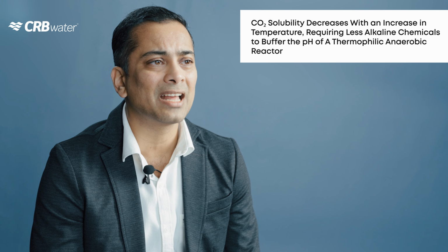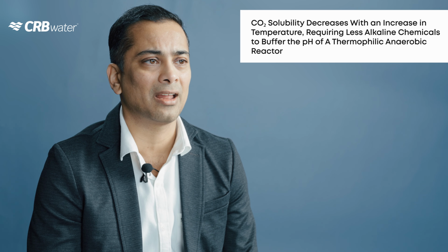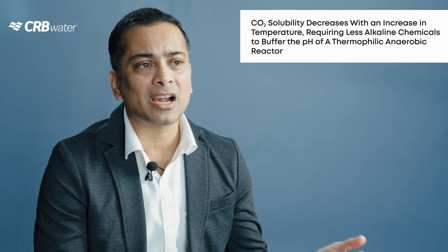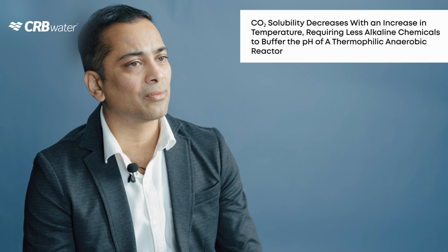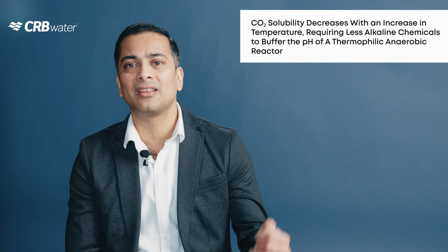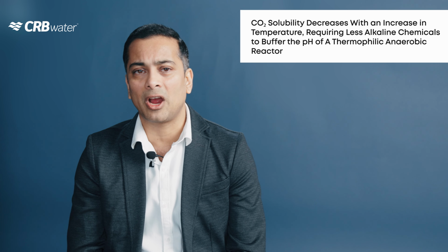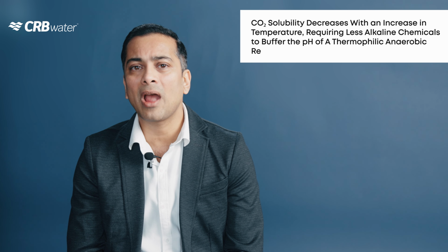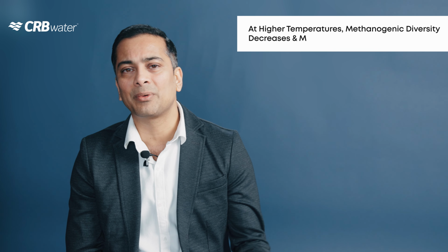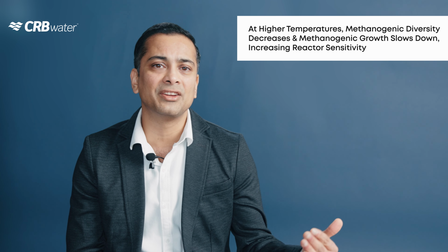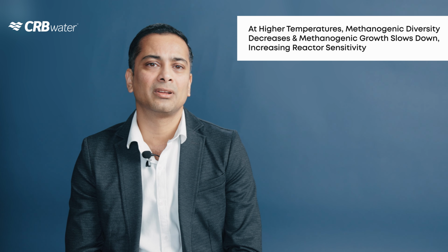Another advantage associated with thermophilic reactors is that the carbon dioxide solubility declines with increasing temperatures, resulting in less carbonic acid formation in the reactor fluid. This can decrease the alkalinity demand in thermophilic anaerobic reactors treating carbohydrates. However, an increase in temperature also carries potential risks that operators and design engineers must be aware of.